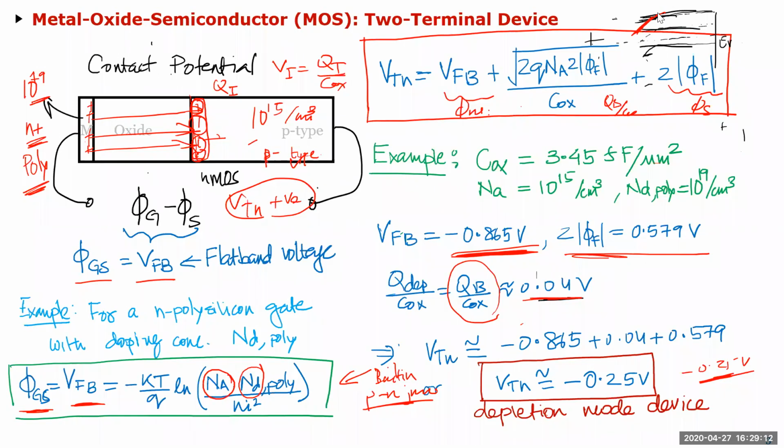Yes, Subham, go ahead. What's the question? So the implanted ions are mobile or immobile? Okay, you tell me, what should it be? Should be immobile. Okay, so tell me why. We have to cancel out the positive. If we implant mobile, then it will conduct.